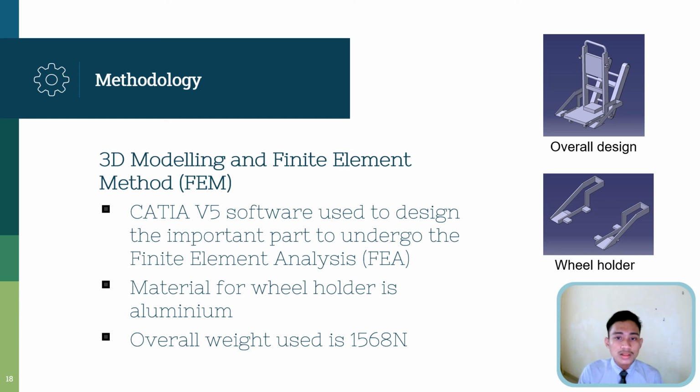The overall weight used in the test is 160 kg, about 1568 Newton, which is the estimated weight for a standard wheelchair and the person on it. The distributed force is applied using two axes, which is tilted about 45 degrees to the ground based on the position of the wheelchair during climbing the stair. This application generates and collects aggregated outcomes for further action.